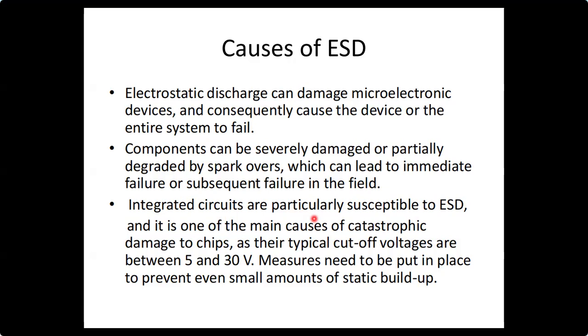It can easily lead to electrostatic discharge, and it is one of the main causes of catastrophic damage to chips, as their typical cutoff voltage is between 5 to 30 volts. Measures need to be put in place to prevent even small amounts of static fields.